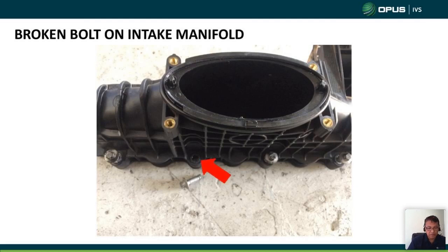And most of the complaints also, while driving on a flat surface, sometimes the fault will not come back or will not light the engine warning light on. Under load, under certain road conditions, uphill under load, the light will come on. And in some cases, you can hear a hissing sound in the engine area.